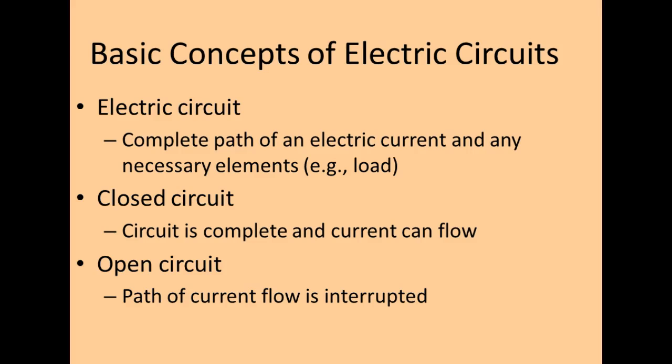What about this? What kind of circuit is that? Series circuit. If I have more than one, and there's only one path, it's still a series circuit. I don't care if there's 100. But if there's only one path and more than one load, and so now it would go plus the voltage from the third load, plus the fourth, plus the fifth. However many we have, they share the voltage. Okay?